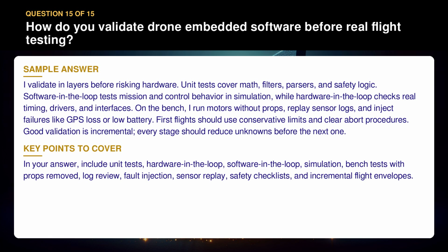In your answer, include unit tests, hardware-in-the-loop, software-in-the-loop, simulation, bench tests with props removed, log review, fault injection, sensor replay, safety checklists, and incremental flight envelopes.